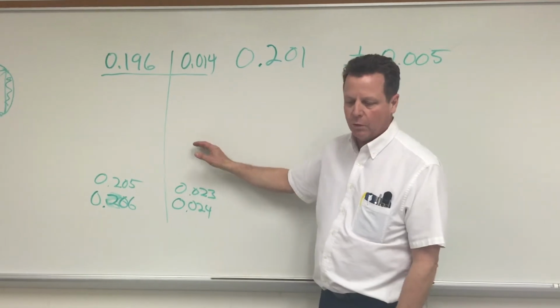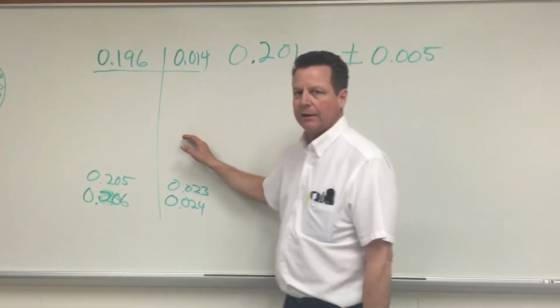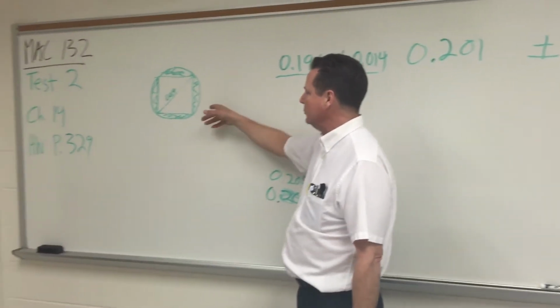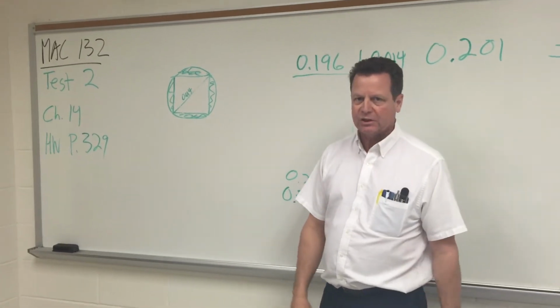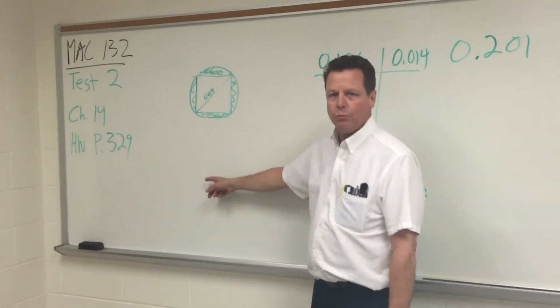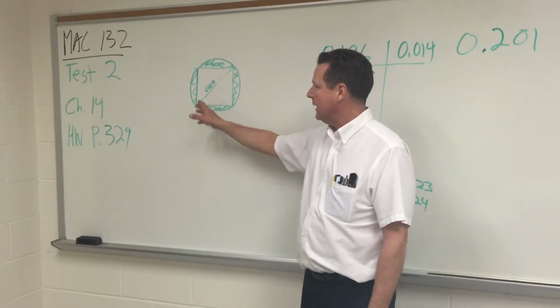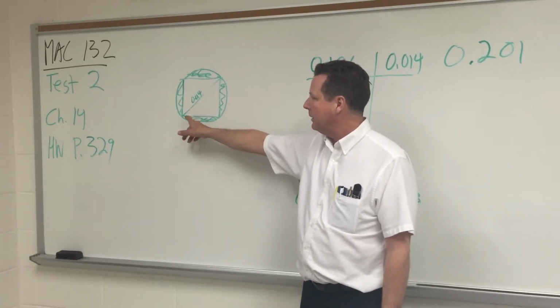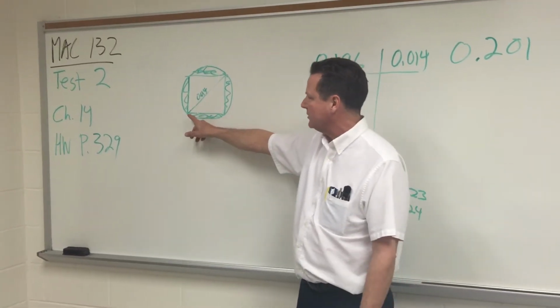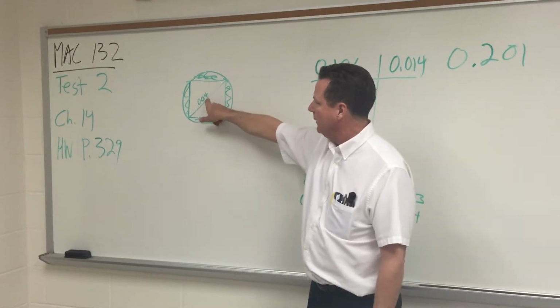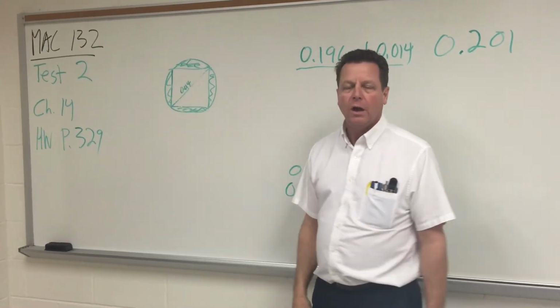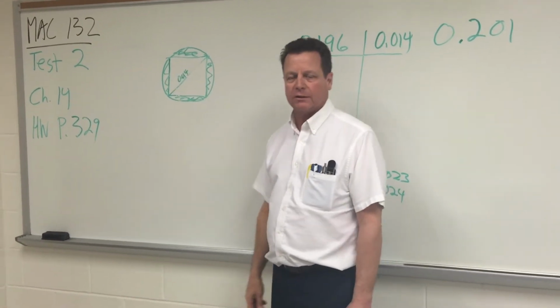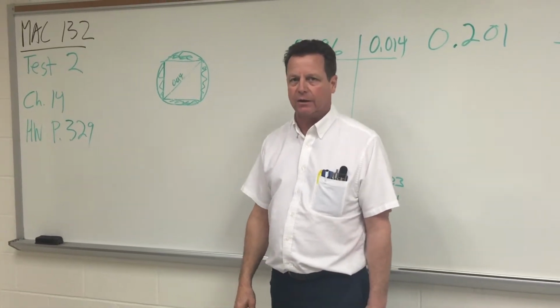We're going to go a lot more into detail on this, and so I wanted to show you the old ways of positioning. Used to be in X and Y, and it would say you had plus or minus 5 or 10 thousandths on the true position of the hole without geometric dimensioning and tolerancing on it.